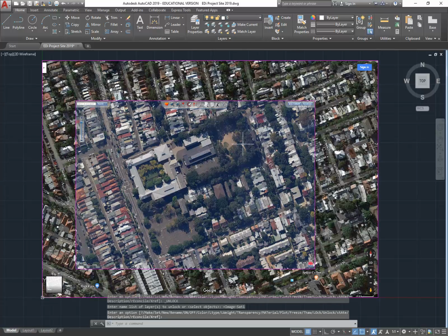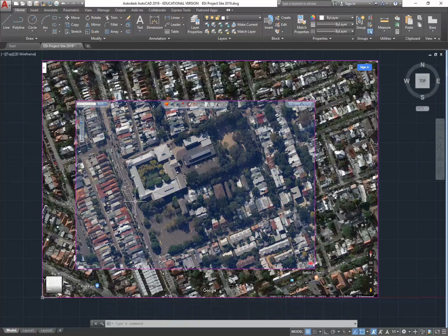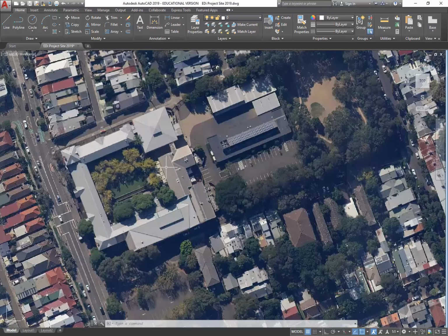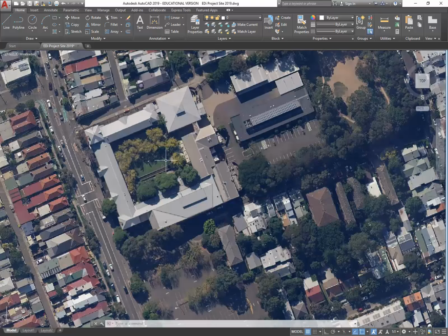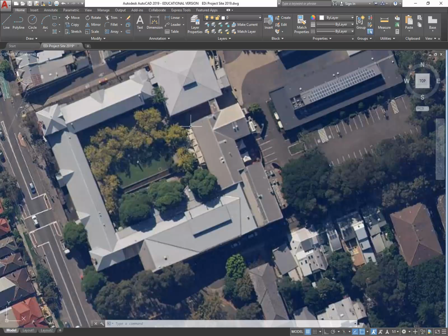So I'm going to unlock that layer now actually, because this drawing is oriented to north, which is fine in most cases, but because you're working on a building, sorry, on the space that's in here, that's at a different angle, it's actually going to work better if we rotate it to work with that space. So it's here. That's the edge of our room. So we want that to be basically our project north.